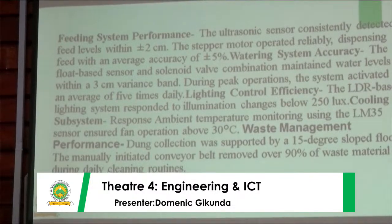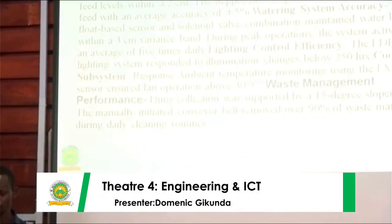So in conclusion, for our system, the feeding system performance was tested and it worked as intended. Same for the watering system accuracy: the float-based sensor and solenoid valve combination maintained water level within a 3 centimeter variance band. During peak operation, the system activated an average of 5 times daily. For the light control efficiency, the LDR-based light system responded to illumination change, down to 50 lux. The cooling system also responded to ambient temperature monitoring using the temperature sensor.